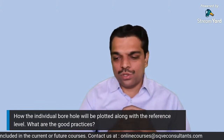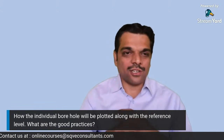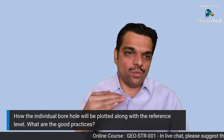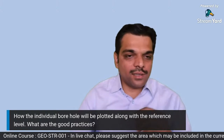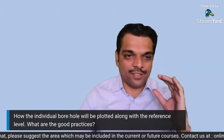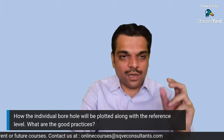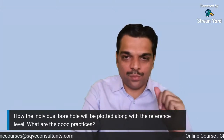If we talk about oil and gas refineries, or a thermal power project, or any big-scale project, it is quite possible that you will have different grade levels. So it is very important that the reference level is indicated in the borehole, and the structural engineer should be able to correlate. This is a very interesting question, so we will showcase a couple of boreholes and how it should be represented in the soil report.